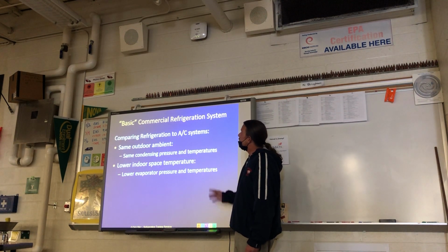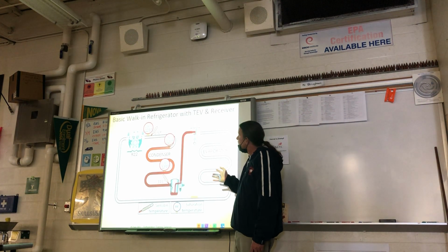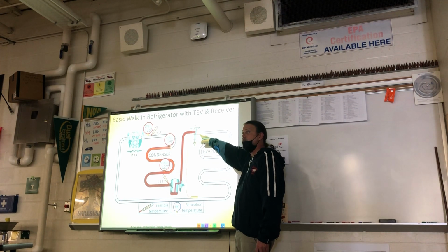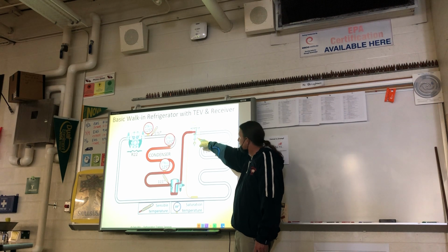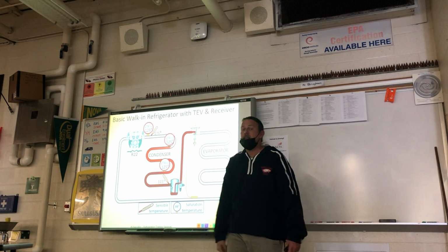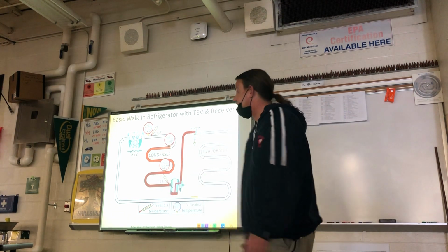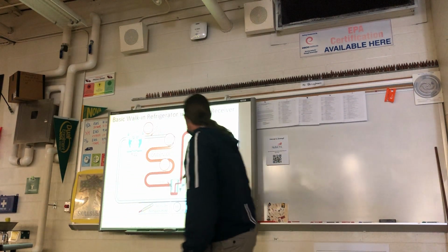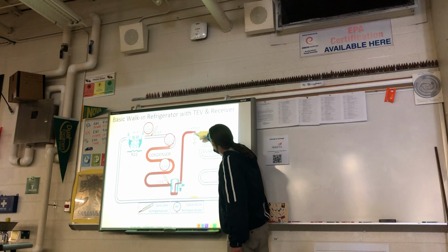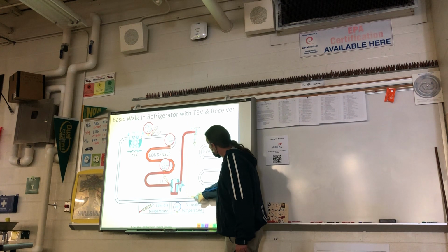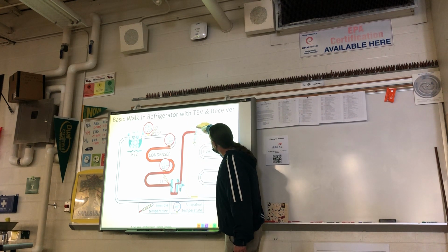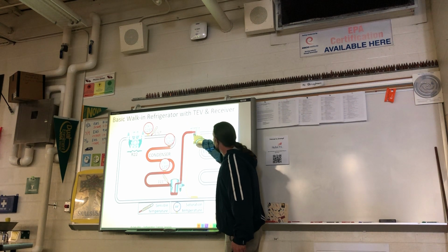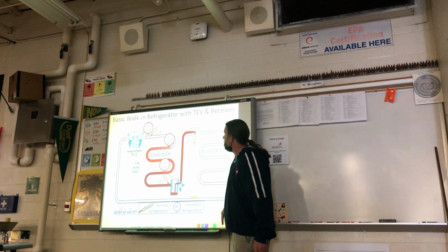Now, refrigeration is going to be a little different. So these are your temperatures, and what have I done? What's different about the metering device? This one has a bulb. Now again, this bulb is attached to a hole like this inside here with a spring against it. So when this warms up, this is going to push more pressure down on that rod, which pushes the spring down, which is going to let more liquid feed through.